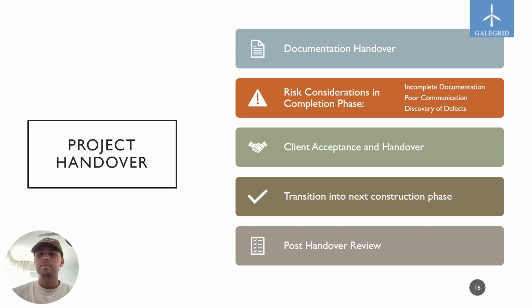The handover phase marks the formal transition from foundation construction to turbine erection. Once all 67 foundations have been verified through testing, as-built documentation and compliance certificates, responsibility is transferred to the turbine installation contractors. Interface coordination meetings confirm foundation readiness, anchor bolt alignment, and crane pad safety. This structured transition ensures that every footing is certified to receive turbine loads, maintaining continuity between teams and safeguarding quality, safety, and environmental performance as the project moves into full turbine construction and operational readiness.